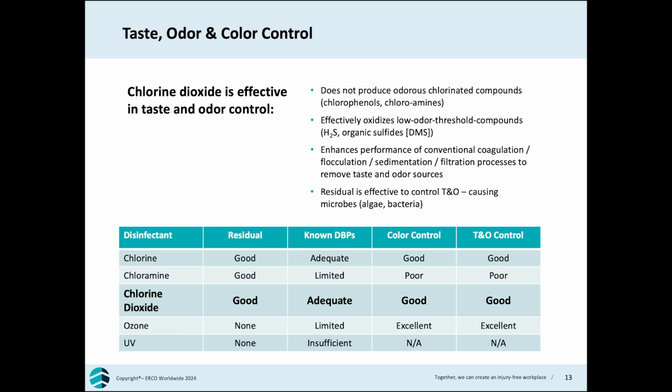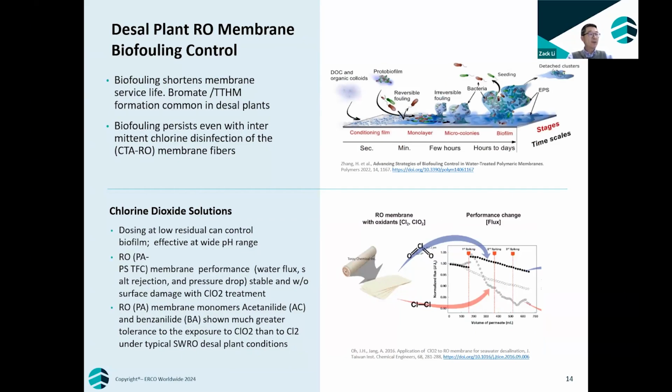So among common disinfectants, chlorine dioxide provides a very good removal of taste and odor and color, and with sufficient disinfectant byproduct formation information, which allows us to plan well-established mitigation control strategies for DBPs, which Alan will present to you momentarily. Chlorine dioxide can also be applied in preventing biofouling of the RO membranes that are used in